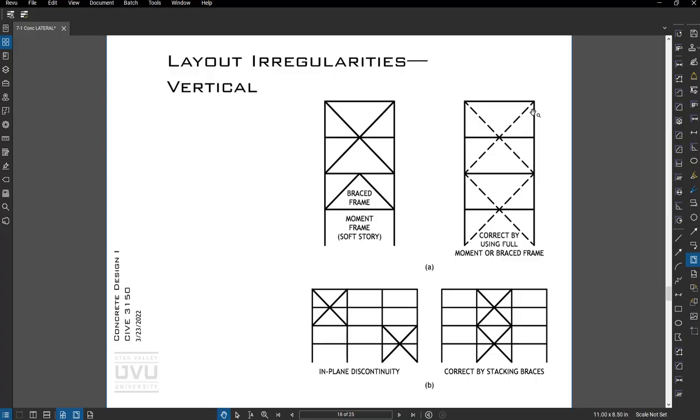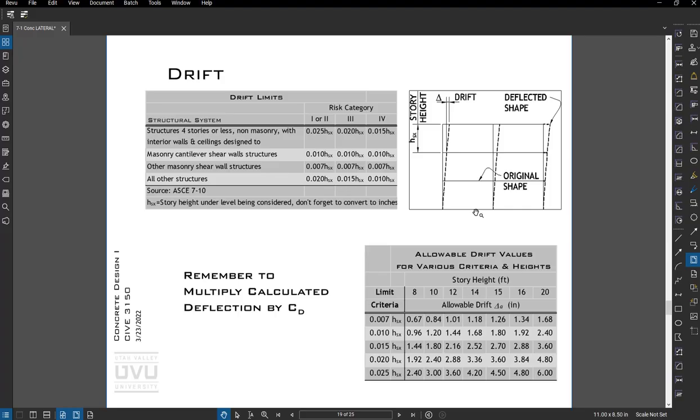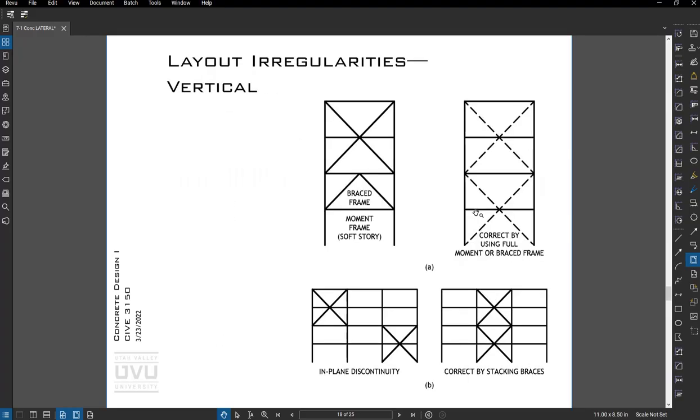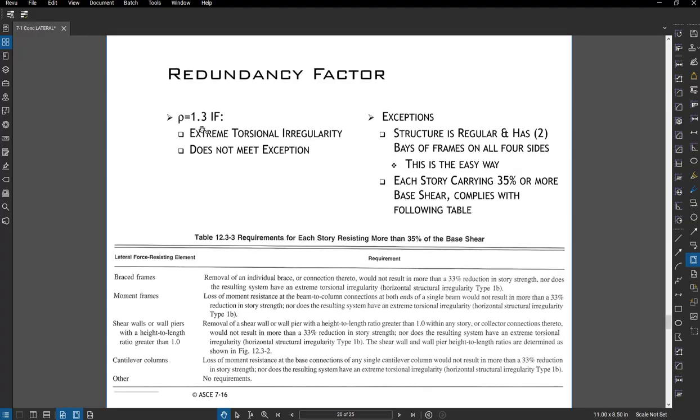And that's something you can talk to an architect about and say, hey, look, if we have poor layout here, I'm going to have to bump up the forces 30% up to 300%, depending on what's going on. So that can be kind of a sell to them. It's not really effective to go to an architect and say, "Hey, for all these technical reasons, we need to do this." Put it in simple terms: schedule, cost, and that speaks volumes.